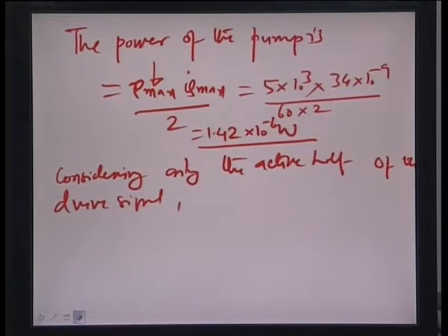So, it is between 0 and 6 volts. Effectively the power cycle is only about half the time, and the voltage given is 6 volts. The remaining half is about 0 volts. So it is just a square pulse or a square wave which is given to control the heaters for the pressure rise or the thermopneumatic force which would close and open the particular valve.